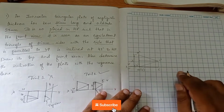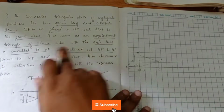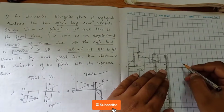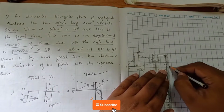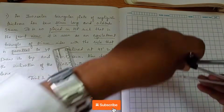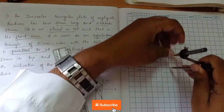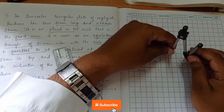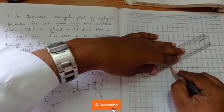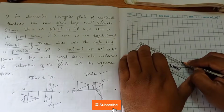But in this second position, the angle of inclination to VP they have not mentioned. Instead of that they are telling we get an equilateral triangle of dimension 25. So I'll be drawing an equilateral triangle here by taking 25 dimension. This problem is a little bit different, that's why we call it a special type of problem. We know how to construct an equilateral triangle of dimension 25.